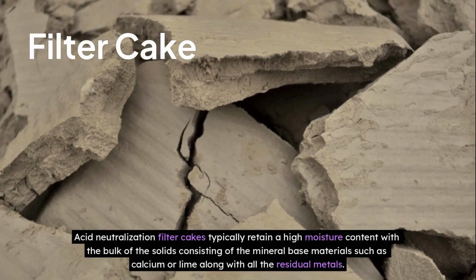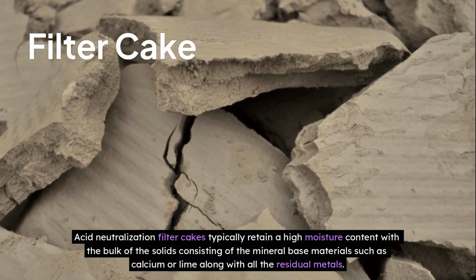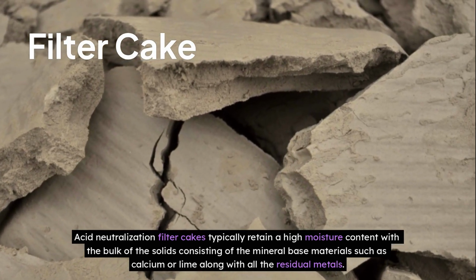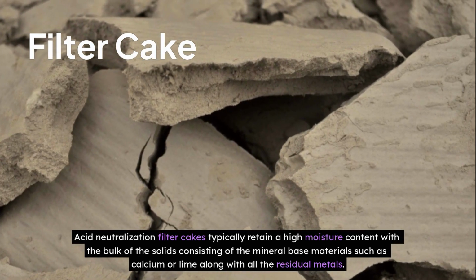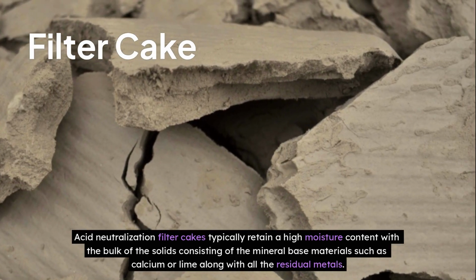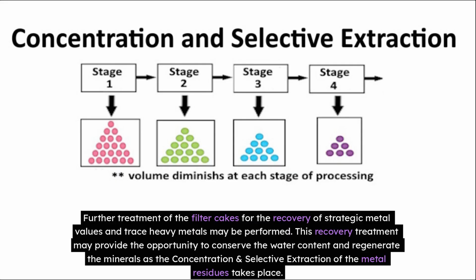Acid neutralization filter cakes typically retain a high moisture content, with the bulk of the solids consisting of the mineral base materials such as calcium or lime along with all the residual metals. Further treatment of the filter cakes for the recovery of strategic metal values and trace heavy metals may be performed. This recovery treatment may provide the opportunity to conserve the water content and regenerate the minerals as the concentration and selective extraction of the metal residues takes place.